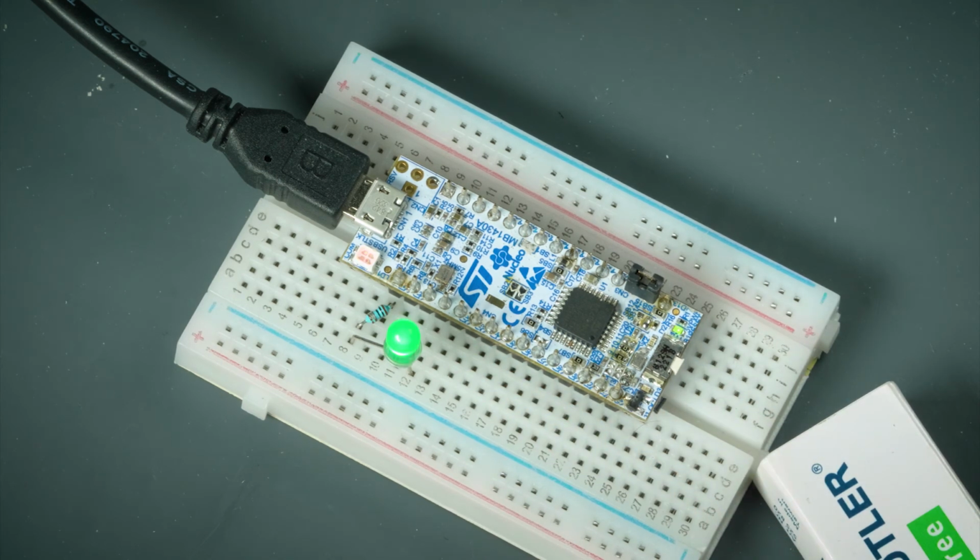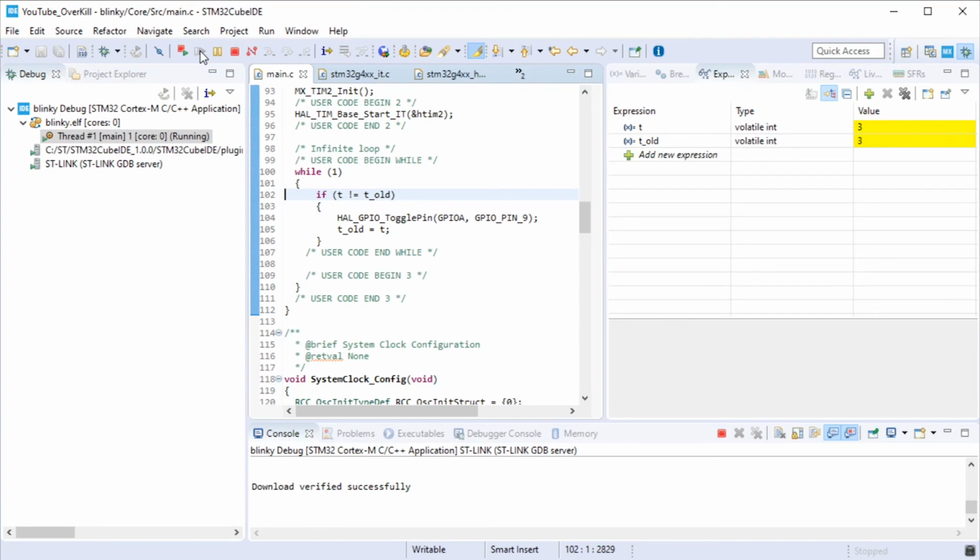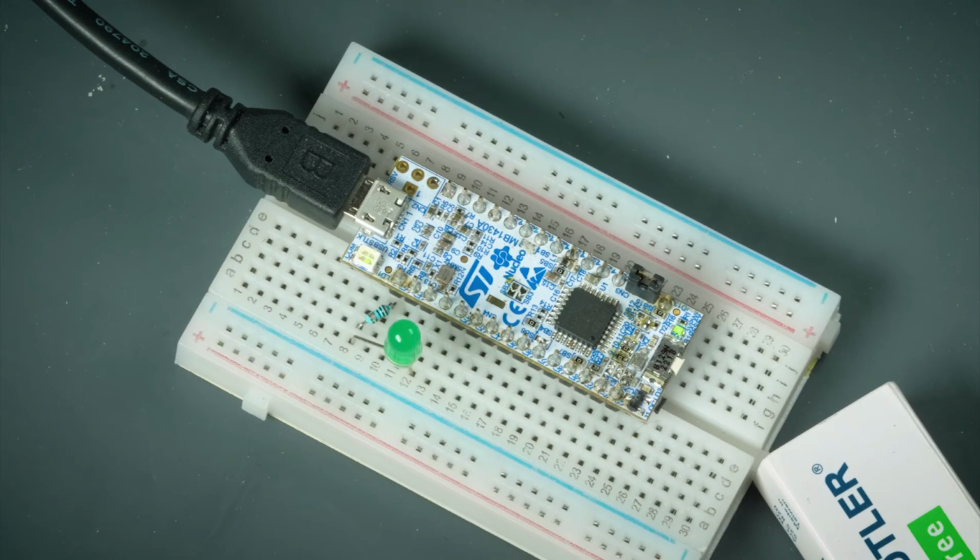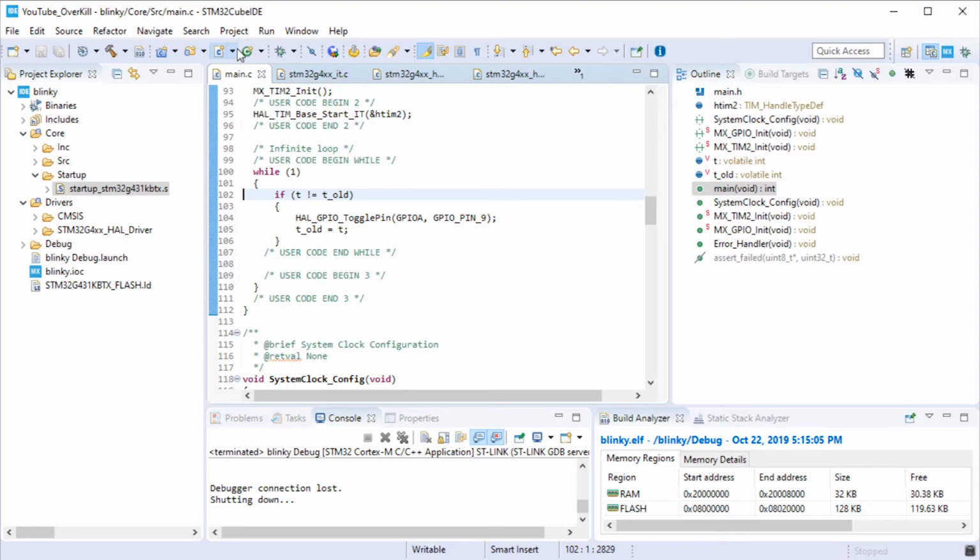Whew. And we're done. So now if you go ahead and you hit the stop button, it'll just keep running. We'll see the LED keep going on and off. And that's because now this is the code that is loaded into the microcontroller. And so every time you plug it in, it's going to run this program unless you specifically are running the debugger. Whew, and there we go.